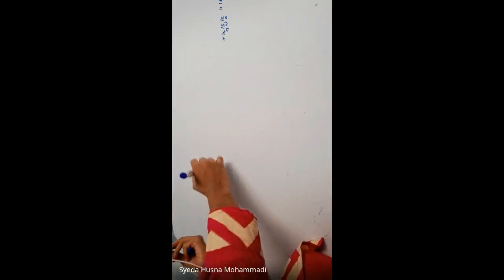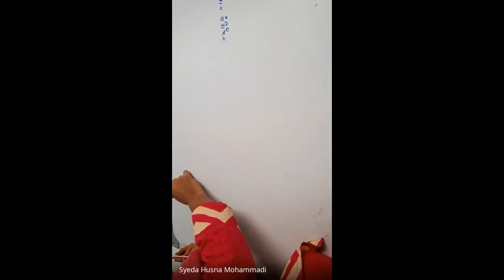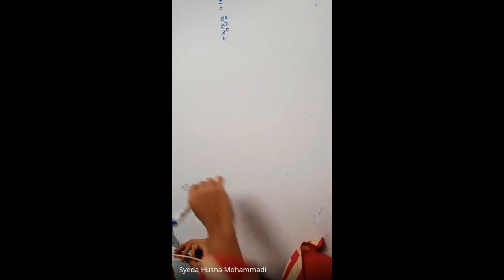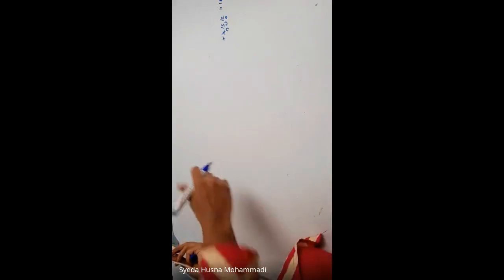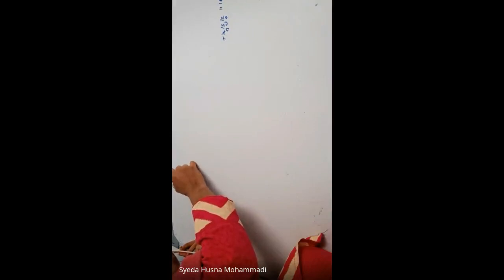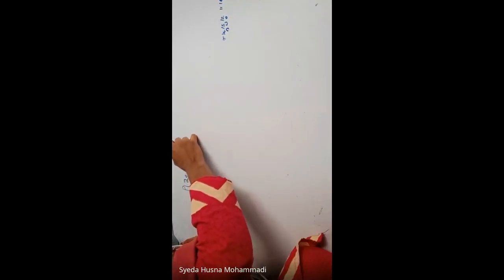Okay, just see here now. It is connected to port 0. Can someone tell me which ports the row is connected to? Row is connected to port 1, pin numbers 20, 21, 22 and 23. So we need to configure it in the direction of the output. So we'll see the configuration.